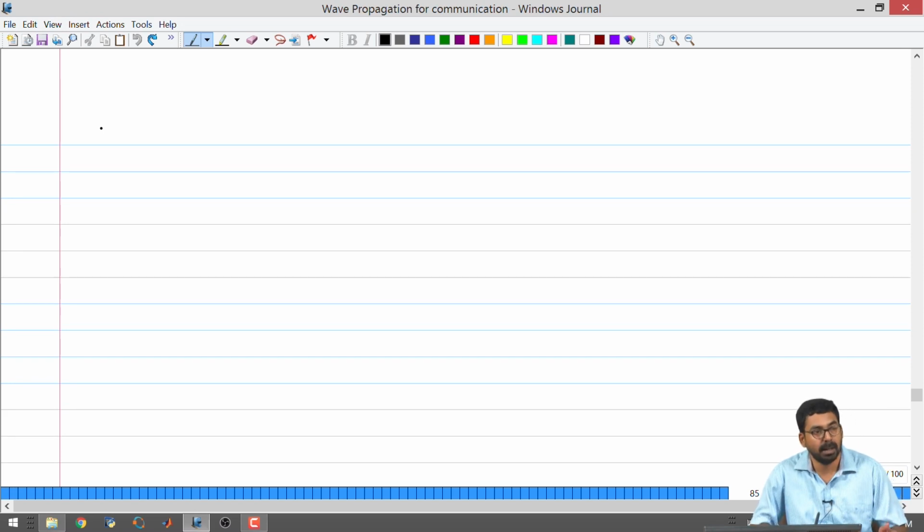The analogous part in transmission line is introducing resistance and conductance in the equivalent circuit for the transmission line section. However, the details are slightly different because here we have both conduction and displacement current densities. So the interpretations and the number of cases are slightly different, but the analogy is exactly the same as what we saw in transmission lines.